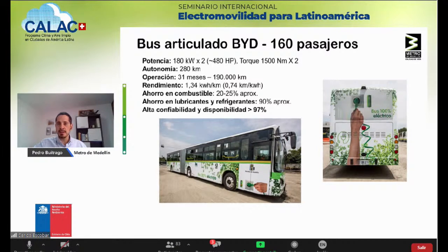Once again, we streamline the powertrain, and this extremely streamlines processes, materials, consumables, interventions by eliminating the combustion engine, by eliminating transmission, by eliminating the differential. The fact that we are streamlining the powertrain from the start can make maintenance reliability of this type of vehicles much easier.